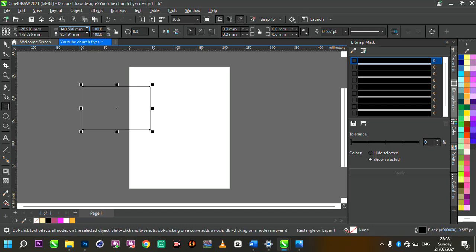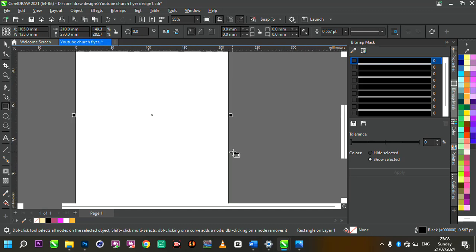Then you move to the dimension specifying size, and then you specify the page dimension which we've already spoken about. So 210 by 270, right? Now the width being 210 and the height being 270. Very good. When done typing in the dimension size, you simply click on the enter key and press P to center align it to the design page size. By pressing P, it centers any element, any object, onto the design page size.